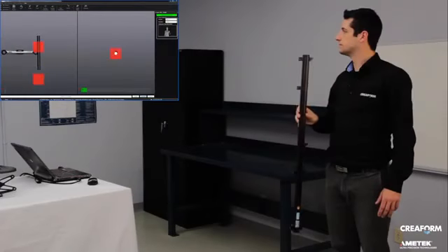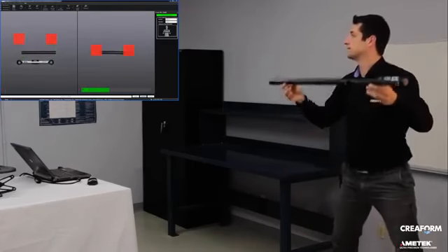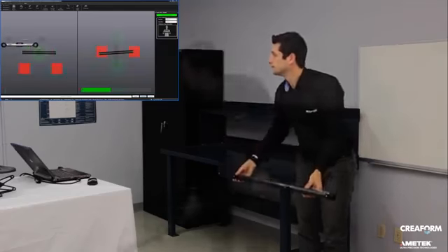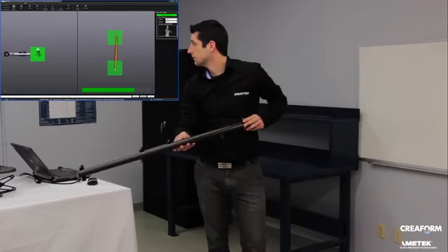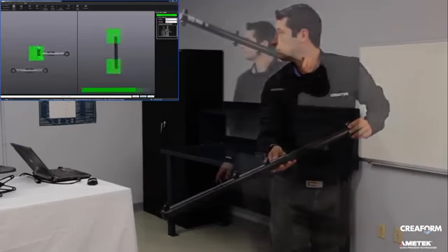The calibration is done through a wizard that guides the user throughout the whole calibration. The user has simply to place the bar in front of the C-track and follow the XYZ positions asked by the VXelements software. This assisted method reduces the human error that could be induced in the calibration.